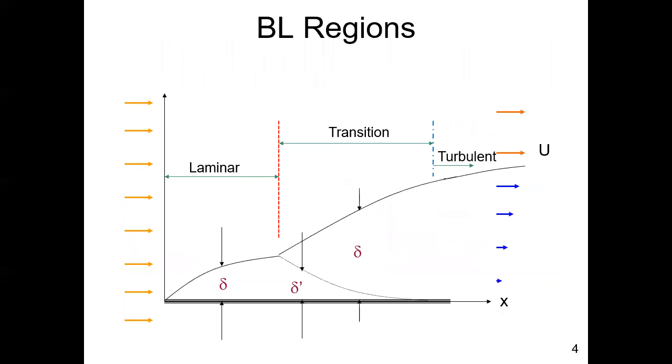After a while, those laminae become unstable in the upper part of the boundary layer. And so up here you have mass movements of the fluid in 3 dimensions, or vortices. That's known as turbulence, and this is a turbulent portion of the boundary layer. Yet down below, you still have this laminar sublayer.